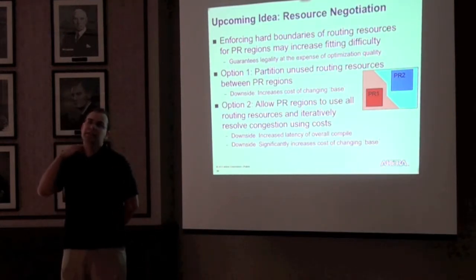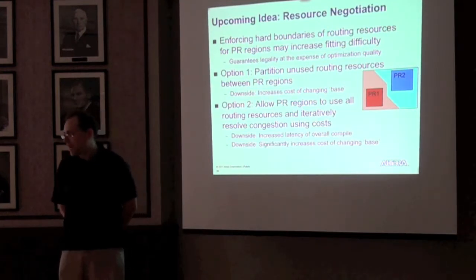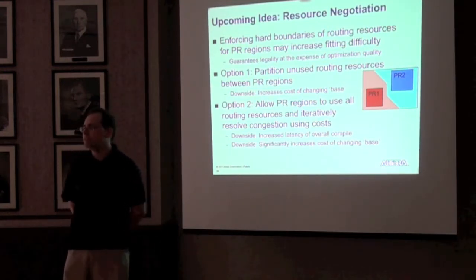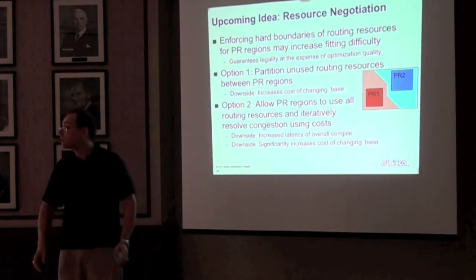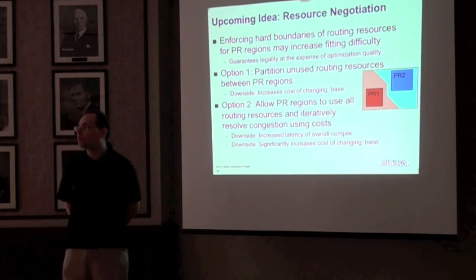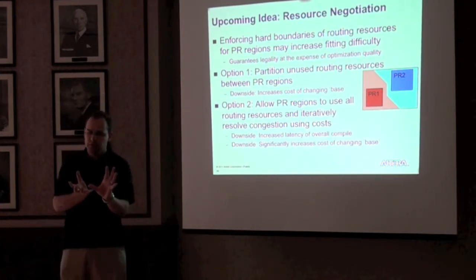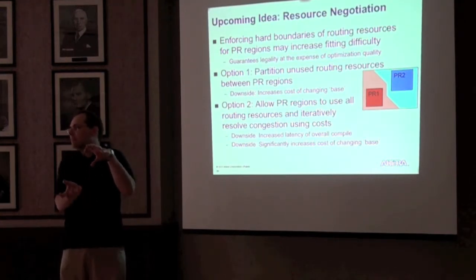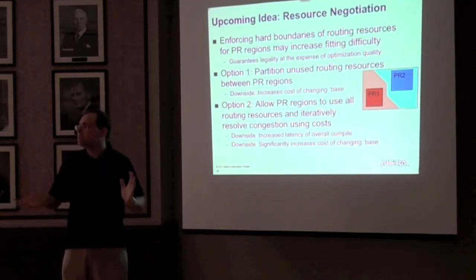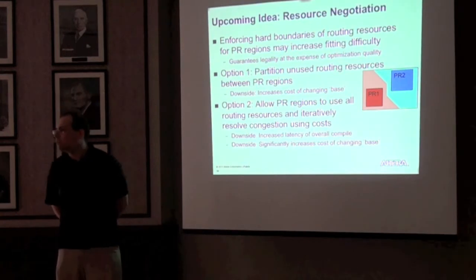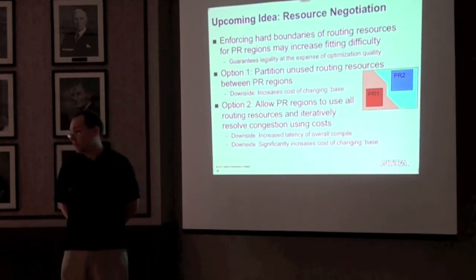So that's an interesting idea. The question is, can I use this framework perhaps for IP or legacy devices? The answer is, incremental compilation is supported for all Quartus families. So a lot of this notion of preserving state and importing placement and routing exists. The ability to insert anchor LUTs doesn't exist right now.